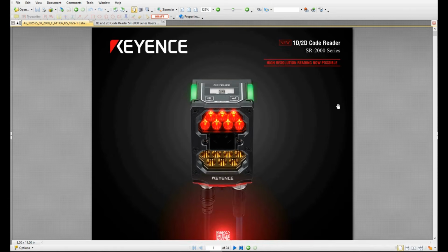So that's all. This is a very brief introduction of this Keyence barcode reader. Basically, it's very easy to use and won't cost you too much time on-site. And there are two important menus. One is this catalog menu. One is the user menu. You had better prepare the communication menu, for example, the Ethernet IP or Profinet menu, according to your controller, that is Allen Bradley or Siemens controller.